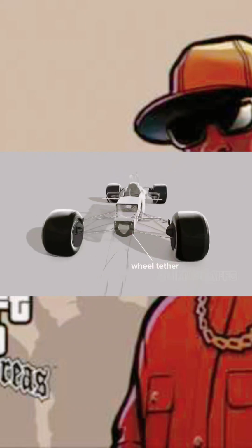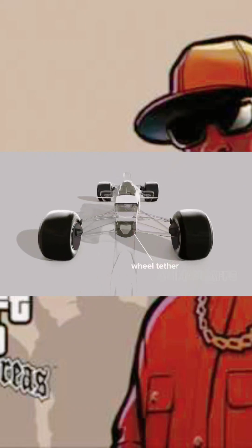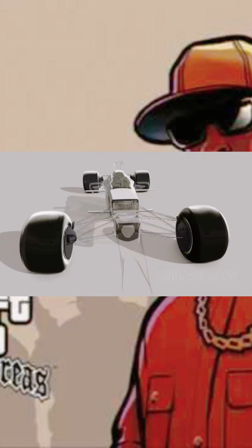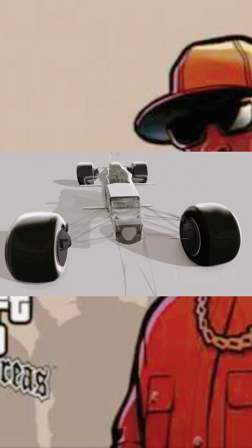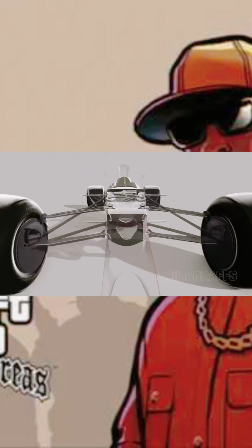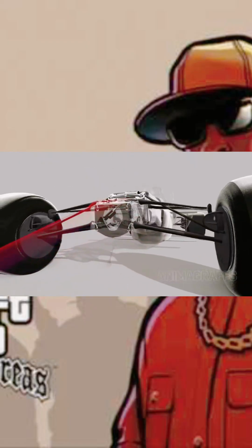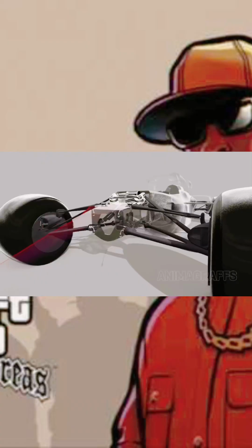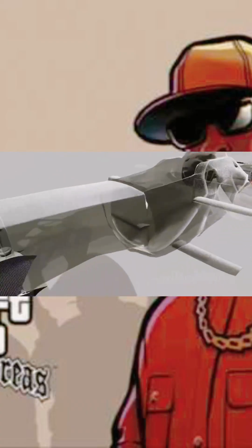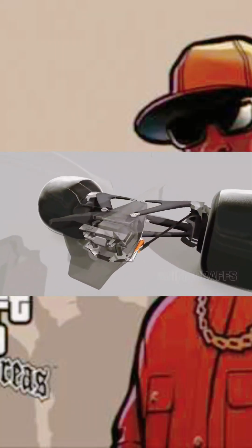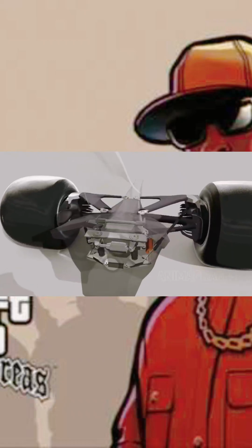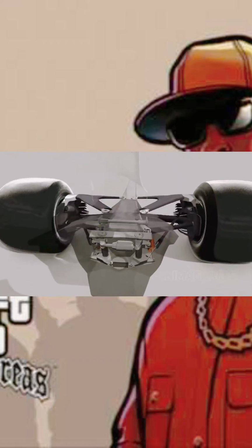All wheels must be attached to the car with wheel tethers. These are strong cables that keep wheels connected to the car in the event of an accident. They're required to pass through more than one suspension element for increased safety. With few exceptions, most exposed suspension elements are either made from or bonded with carbon fiber for better aerodynamic forms. This is another major reason suspension parts are packaged inside bodywork, away from outside air wherever possible.